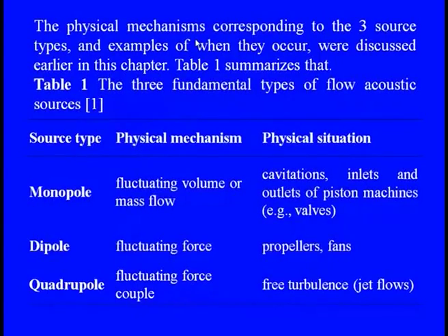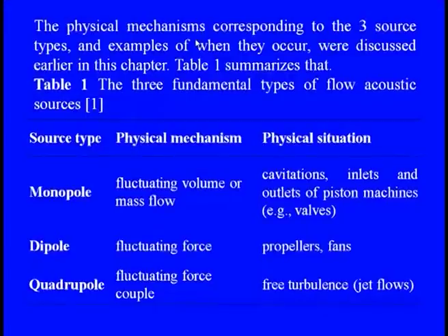So, we need to understand the basic physical system and check exactly what fluctuations there are in the mass flow or in the entire volume, because there are situations in which cavitation, inlet and outlet piston parts, or inlet and outlet walls, or even different cross sections of the pipes with abrupt changes, certainly give clear situations where we have sound and vibration generation.